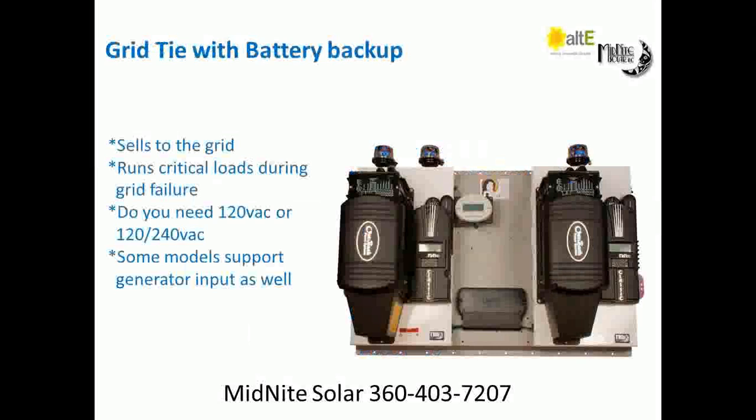Now the next question is, how many watts of PV do we want to put up? If we want to put up, say, 6 kW of PV, then we're going to need at least a 6 kW inverter in order to sell that all back. Otherwise, we're just wasting PV. So the two things you want to look at with a grid tie with battery backup are: what's the biggest load you want to run in any one second, and how many watts of PV do you want to put up? Those two are going to help you size the inverters and the charge controllers.